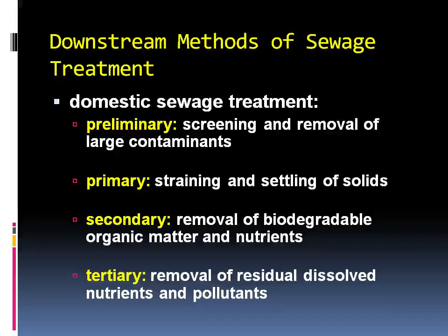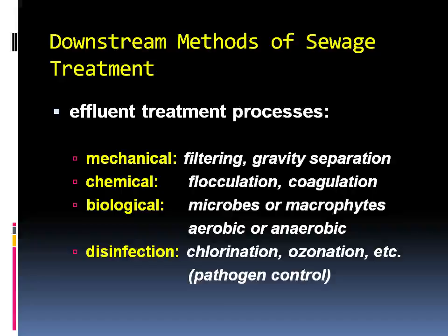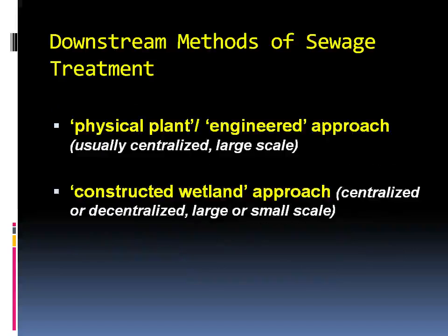Primary treatment is a mechanical process which simply removes solids. Metal screens stop large solids, sand and small stones settle in a grit chamber, from which the water passes into a sediment tank, where its rate of flow is sharply reduced and small particles settle as sludge. Scum at the top is removed. The quantities removed at this stage can be huge. Primary treatment is able to remove organic material responsible for 25 to 30% of the biological oxygen demand of the sewage.